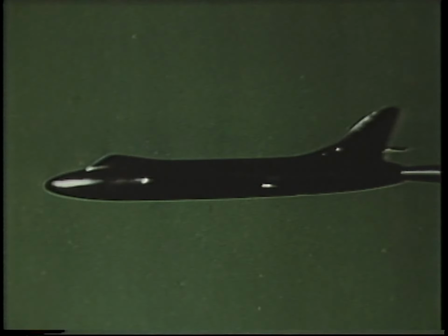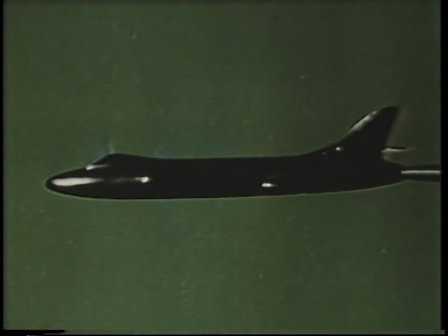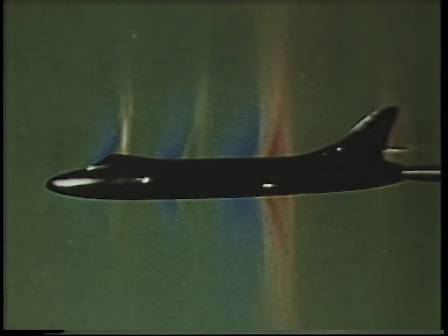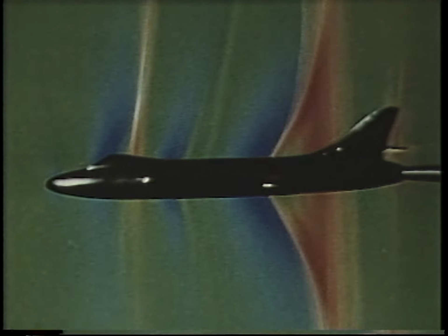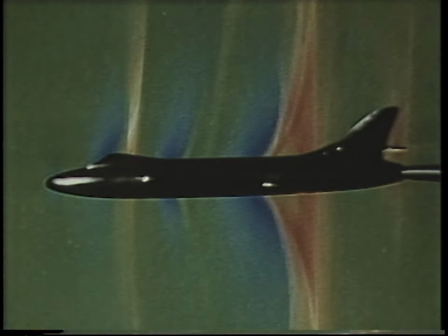And here's the real thing in the wind tunnel. The wing has just passed its critical Mach number, and there's the shock wave, red, because it's a sudden, sharp increase in pressure. But shock waves don't only form on wings. Wherever the air speeds up enough in its passage over the aircraft, on cockpit canopy, fuselage and tailplane, there too, shock waves will form.